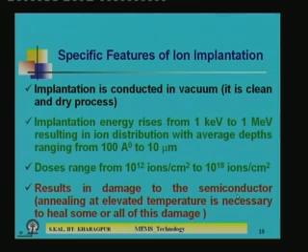Other points are also there. Implantation is conducted in vacuum, so you can expect a clean and dry process. Diffusion is not in vacuum, it is in normal atmosphere, so there is a chance of incorporation of impurity atoms other than the dopant atoms. So it is a clean environment, a clean process in ion implantation.